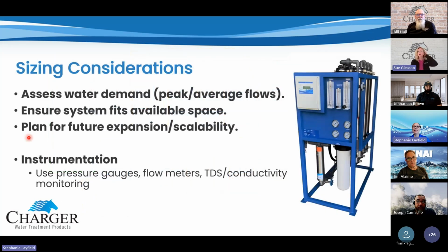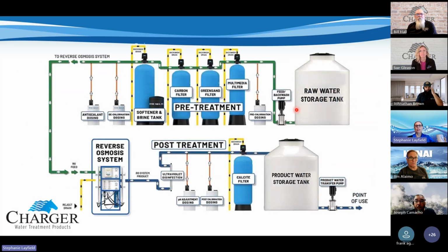Hey, Stephanie. Yes. David had asked, wouldn't it be better to add the chlorine to the storage tank earlier in the chain? That would be smart on that one. Yeah, I'd probably want it up here so that it has that contact time. Are you talking about the raw water storage tank or the product water storage tank? The question.